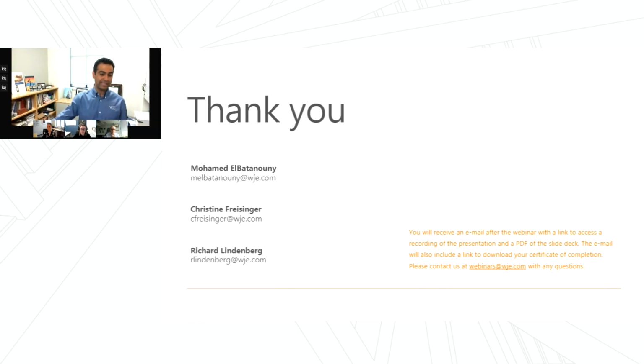So for the SU example, we did need the preloading to make sure that we are actually engaging the new columns that support the structure to take some of the dead load. The human-induced vibrations, which are very small in amplitude and are caused by human walking, can be mitigated effectively. So dealing with existing structures is a little challenging, but with good designs, you can do it without undesired effects.